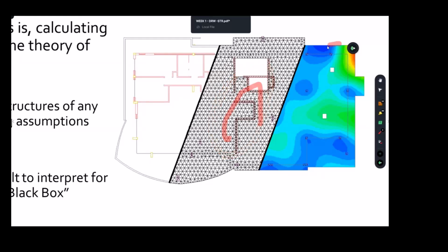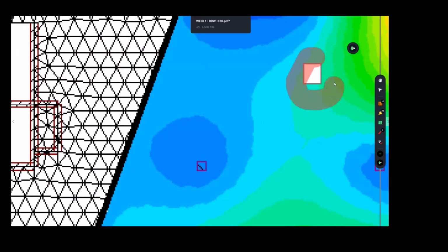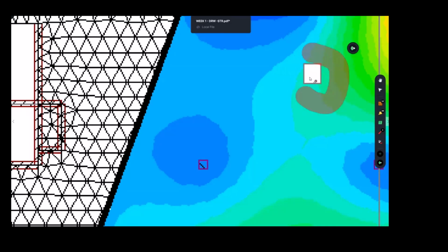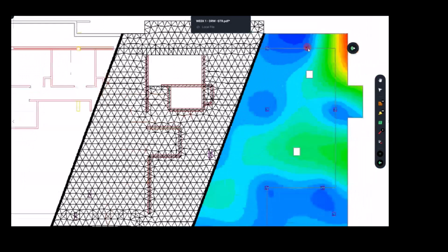Now, not only that, after you mesh it, you can make other clicks and the software will start giving you these contours. These contours can represent the bending action. So here we have positive bending, obviously, because here we have columns. This is column, this is column, this is column. The whites represent a void, like a hole in the slab. So it's not column, column, column.